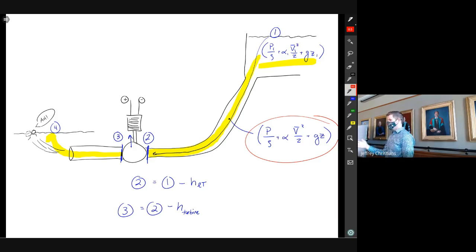Now, if on the other hand you change the minor loss coefficients by a factor of 10, and your efficiency for your whole system goes from 70 to 69.94, you go, wow, these don't matter. Nobody cares. We'll do it later. It has almost no bearing on the performance of the system, so we don't need to worry about it. Let's focus on the higher priority things. Those are the kind of questions you want to be asking, like pipe diameter. If you go from a 5-meter pipe to a 6-meter pipe, do things change a lot, or just a tiny bit?